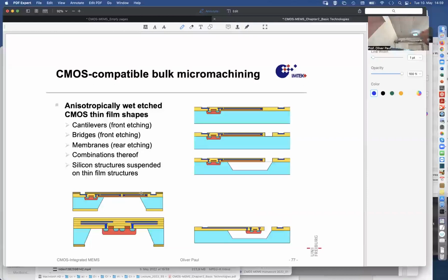If we have designed that field oxide to be so large to receive that etchant, and if the etchant doesn't attack silicon oxide so much, if we stop fast enough, then that field oxide will be mostly intact, and everything that is on top will also be intact. And what do we have available? We have available other materials of the CMOS process, like polysilicon, other dielectric layers. We have metal 1, metal 2. We might have all kinds of other materials if the CMOS process is more complicated. And those can be designed into useful structures.